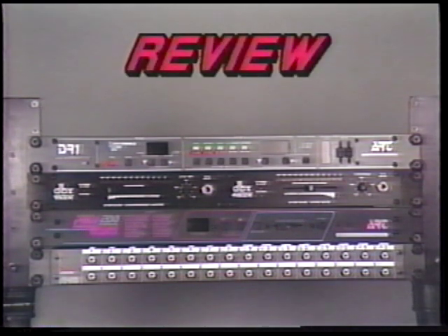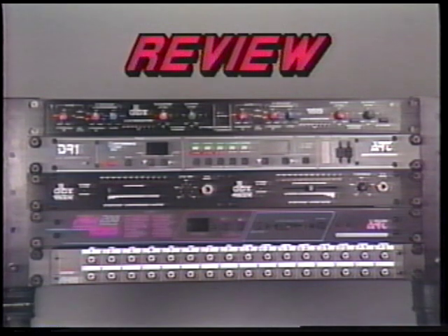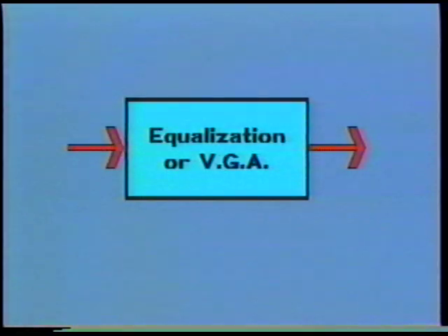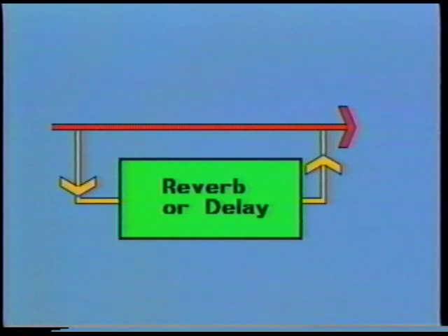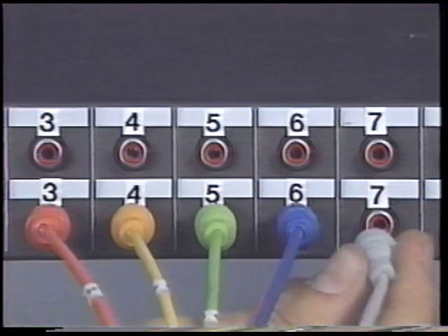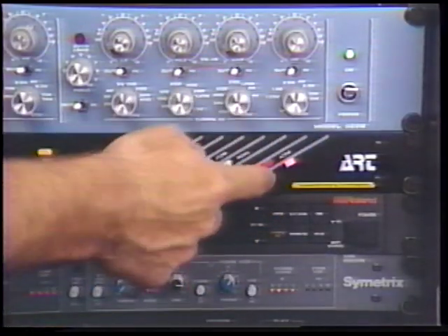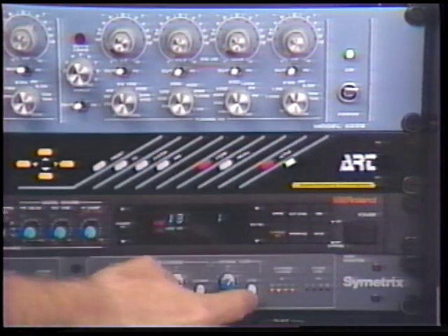We've completed our introduction to the 4 basic building blocks of signal processing. All of them work by shaping or combining audio signals. Equalizers and variable gain amplifiers selectively shape the amplitude of a signal and should be placed directly in the signal path. Delay and reverb devices recombine a processed signal with its source and should be placed in the side chain of the signal path. You should set these devices up so that they can be used flexibly in varying sequences and combinations. They can be used during the recording process, again when combining tracks, and during the final mix to shape the overall sound.